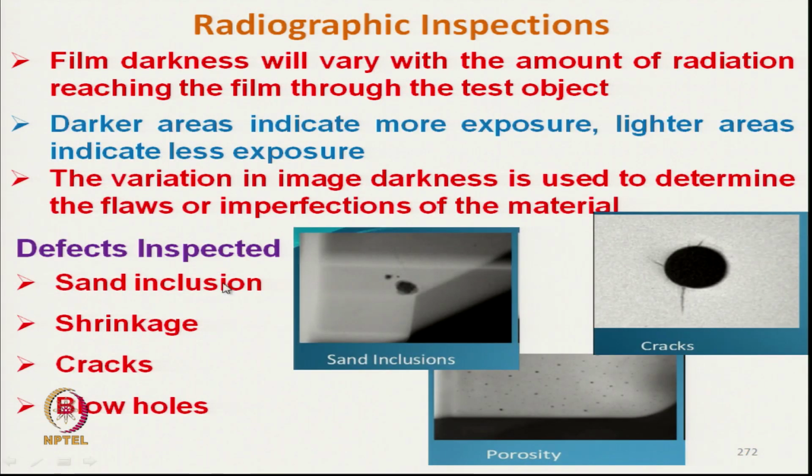These are the defects inspected: cracks, sand particles or porosity. We can get an idea about internal defects present in the composite through radiographic inspection.